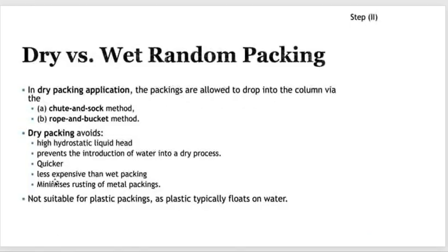But if you target mixing or good mixing to make turbulent flow or something like that to ensure good mixing, you can go with the random packing. Here, I want to make clear to you, there are two ways to install the packing inside the tower. There is a dry process and a wet process. The wet process works as follows.